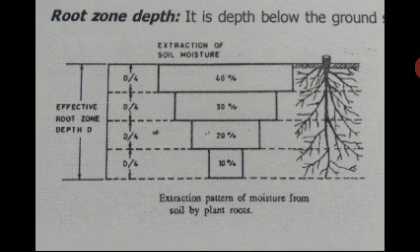Ultimate wilting. When ultimate wilting occurs, the plants are completely wilted, that is, the plants die away and they cannot recover from wilting even after the addition of water to the soil. The ultimate wilting point occurs at the hygroscopic water content.